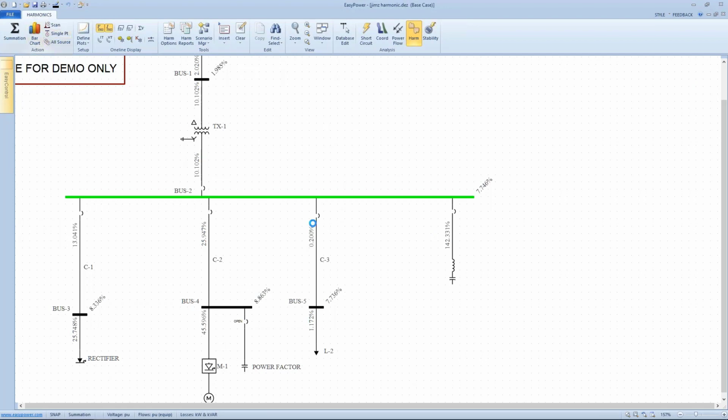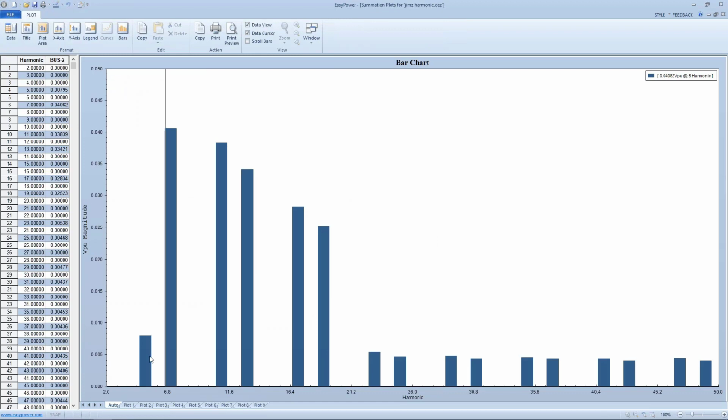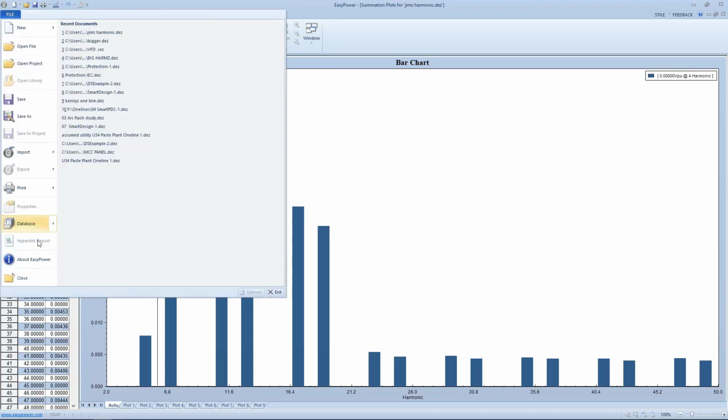The thing I wanted to illustrate is that we have considerably reduced and filtered out the fifth harmonic, which was considered to be the problem. And these others, while they're still present, are much less of a problem because their effect is going to be, resistance-wise, a contribution of the root squared of that particular frequency, of that particular harmonic.